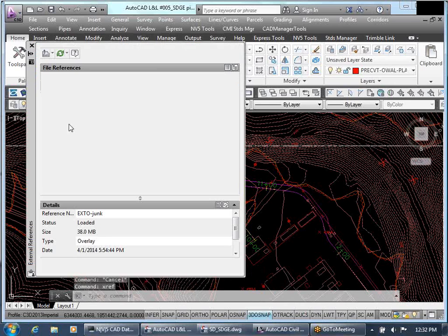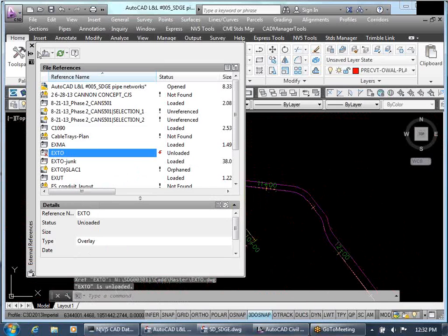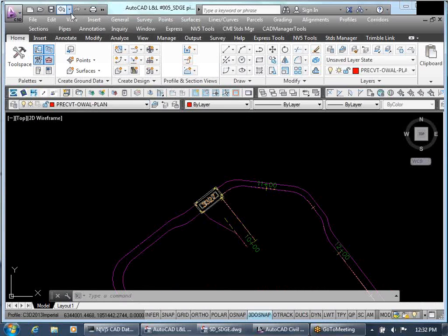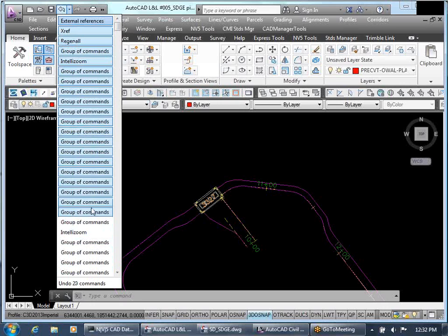So now that I've shown you that, I'll unload my XREF for the topo. Jarrod, the update command where you can pull down ties into that shortcut. It's nice when you're trying to back up steps too. This will undo a bunch of commands rather than hitting undo and spacebar 20 times like I did, especially if you're using commands that are easily identifiable, like that CC command.